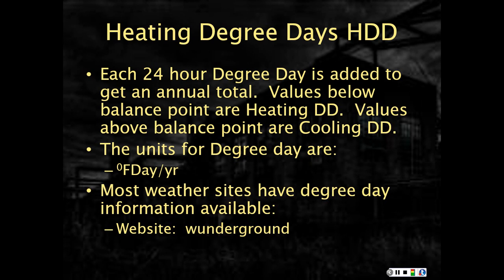Now it's important, this next line, and make sure you understand this. The units for degree day are degree Fahrenheit times day divided by year. Make sure you're using the annual total and not just one day's worth of degree days. So it's degree Fahrenheit times day divided by year. Most weather sites have degree day information available, such as the website Weather Underground.